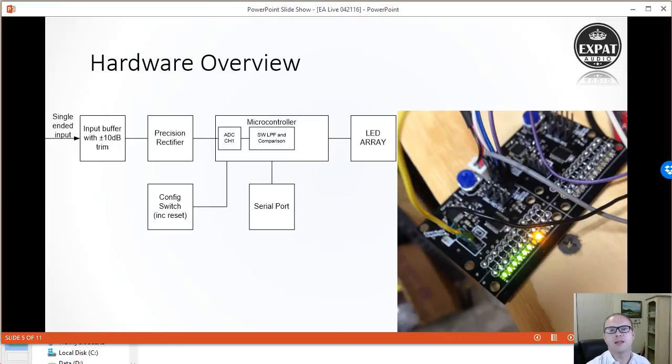To put it into perspective, roughly every bit in your converter is worth about 6 dB of dynamic range. So if we had sacrificed one of the bits, then we would have gone from 10 bits, 60 dB dynamic range, down to 9 bits, which would mean 54 dB dynamic range, give or take. So I wasn't quite ready to do that because I wanted the entire dynamic range as much as we could.